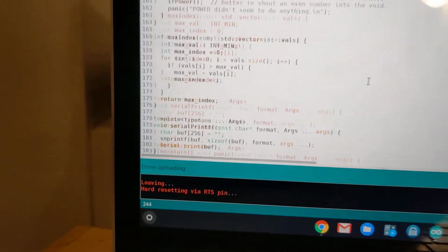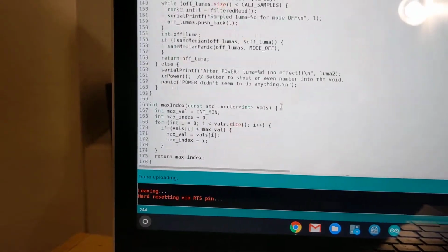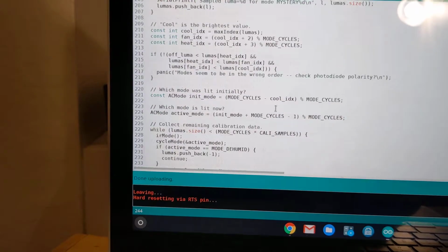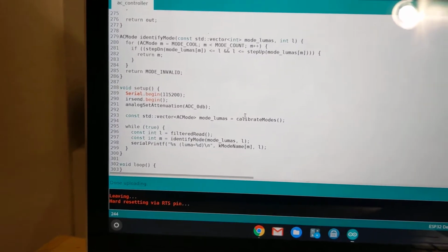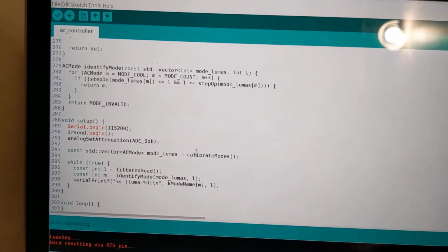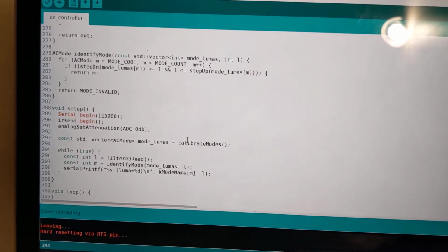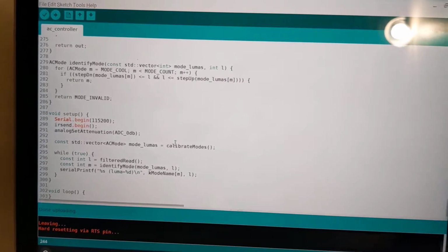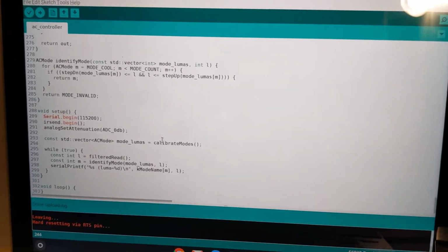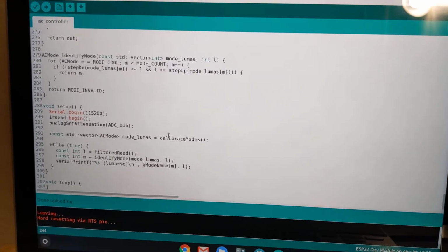Yeah, so this is just kind of like Arduino C++ code. It sends IR, and it turns out that I don't know if I did the photodiode in the best way, but it's actually just literally a photodiode connected to one of the analog inputs. There's no resistor, it's just ground to input. I was trying to use a 1 mega ohm resistor initially, but it turns out that just doing photodiode directly to input turned out to be more stable. Like I could get more predictable results.